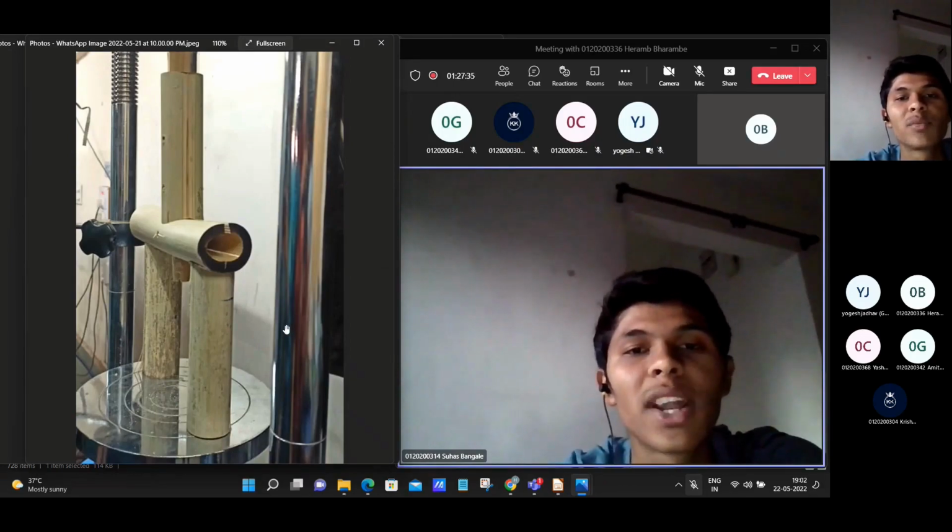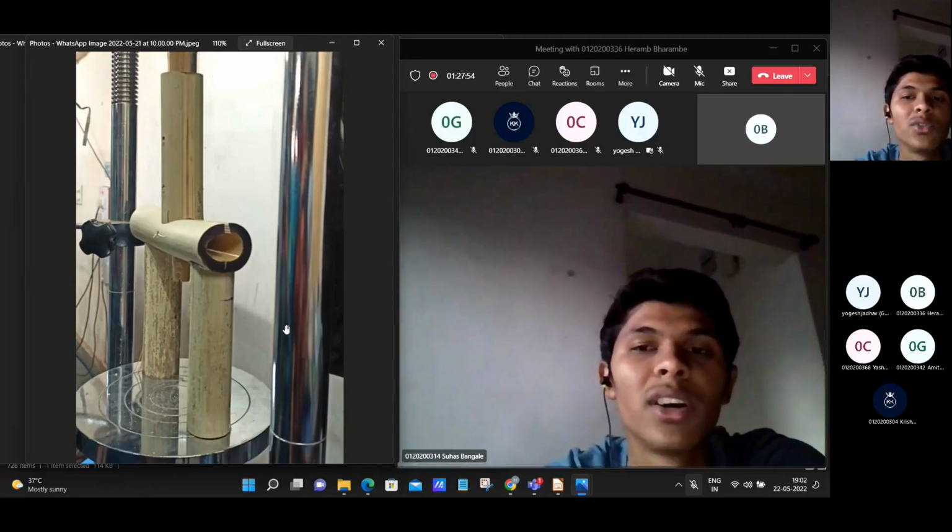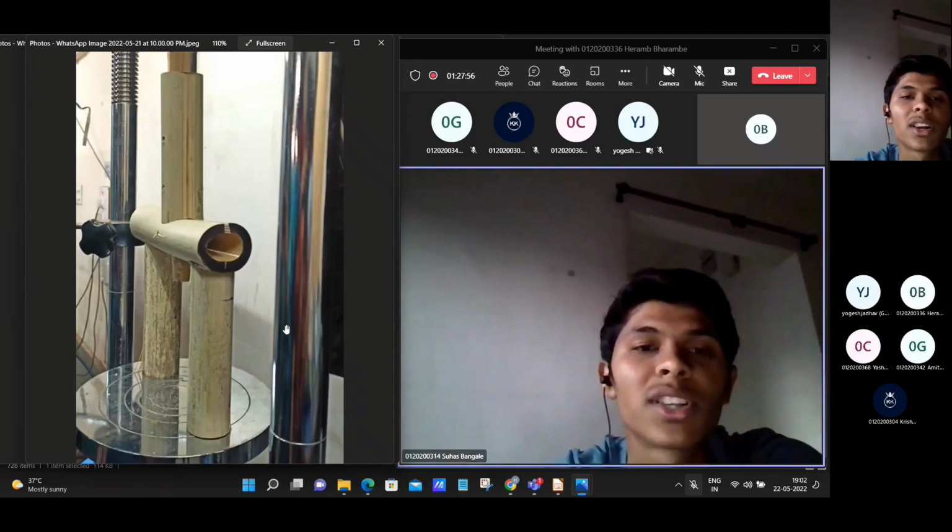The result of this analysis provided an overall basis of determining the effectiveness of the joint. The result of this test seeks to provide reference loads for when mortar should be inserted into the anchor joints, which would help to reduce the cost associated with mortar use and give the structure additional lightness. So through the structural analysis and references available, loads were calculated for the specific bamboo canopy structure.